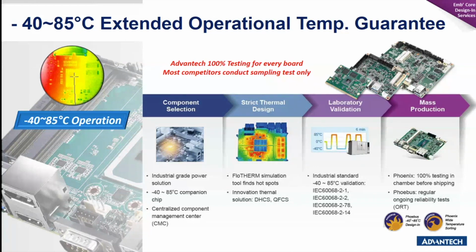You have to ask. So for example, when we select wide temperature range, we have to be very careful of component selection. Just to take a simple example, certain components are not rated to go that high. For example, some Intel LAN parts can go up to 80 or 90 degrees, and there are some that can only go up to 70 degrees.